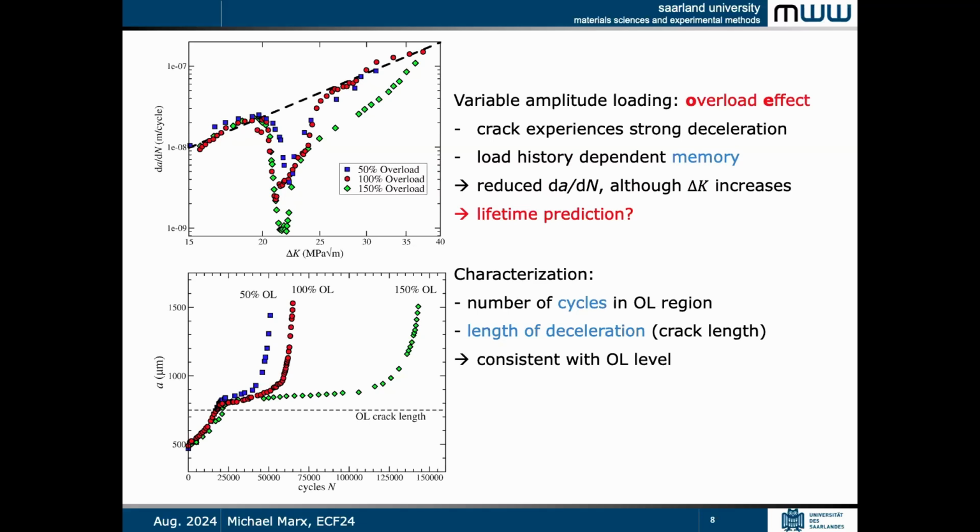And if you measure the crack length as a function of the number of cycles, it looks like this. Maybe if you would just extrapolate the normal fatigue crack behavior, it would go in this direction. And if you think 1.5 millimeter is the final crack length, then by the overload you increase your lifetime from 25,000 cycles to 50,000 cycles by 50% overload, up to nearly 150,000 cycles by 150% overload in this case. So this is the